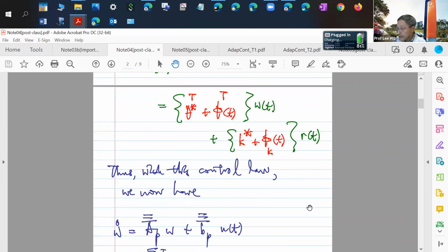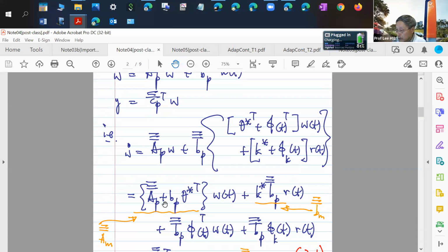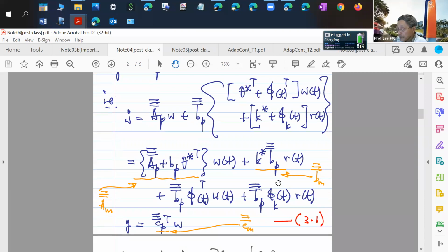If we substitute this control law in, substituting in those perfect gains, you already saw from our earlier analysis that these are 2n gains for the 2n order non-minimal realization. When you put the 2n gains in, this exactly comes out to be your reference system.